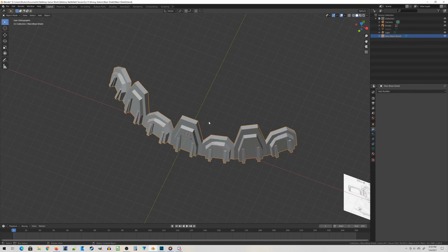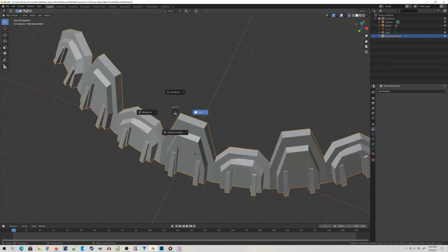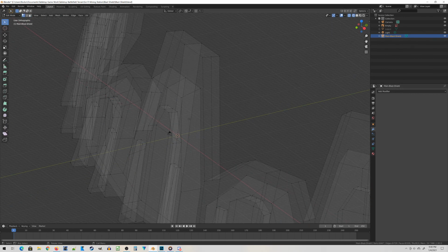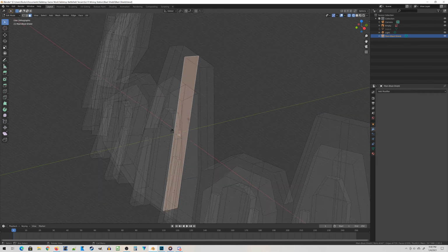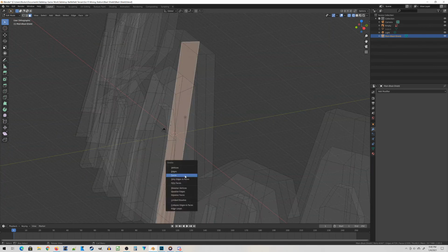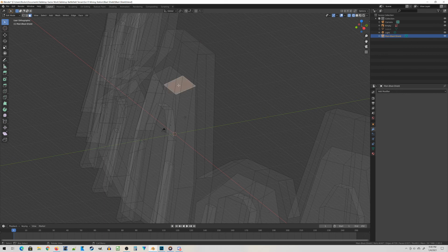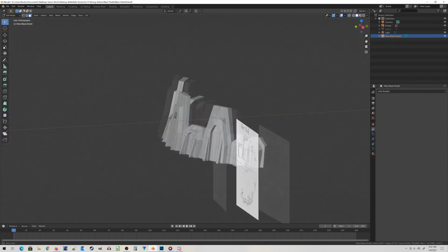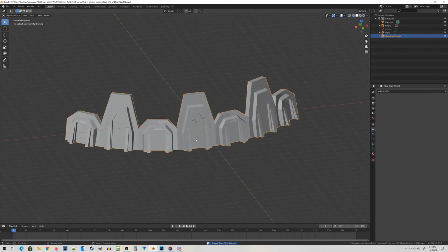But once again, there's interior faces in there. So let's jump to wireframe mode. We're going to hit tab to edit mode, go into face select mode in the upper right hand corner, and play hunt for the tiny black dot that corresponds to the 2 faces we need to remove. There's one of them. Press X, choose faces, and there should be one more here. Nope. There we go. So that little dot should be roughly in the middle of the face, if that helps at all. Press X one more time, delete it, and now we've got a complete solid object.